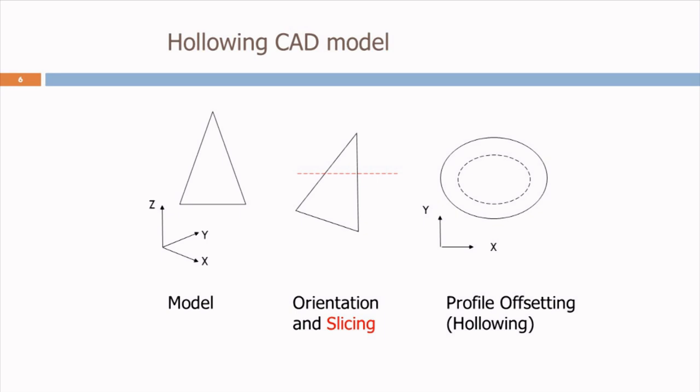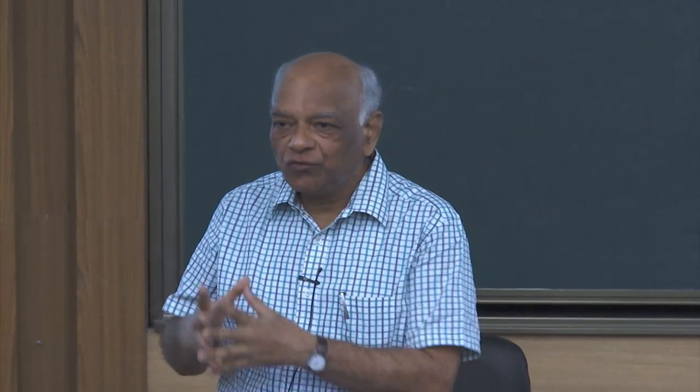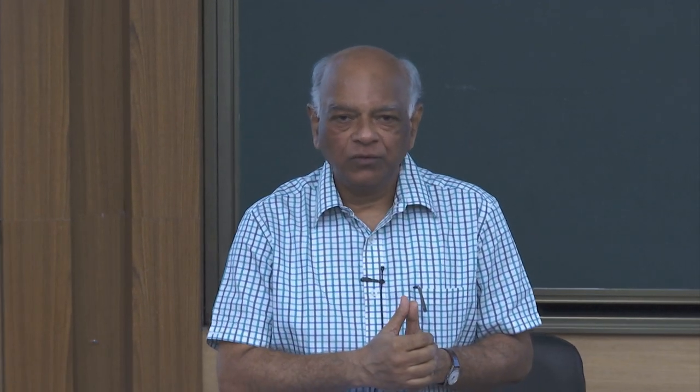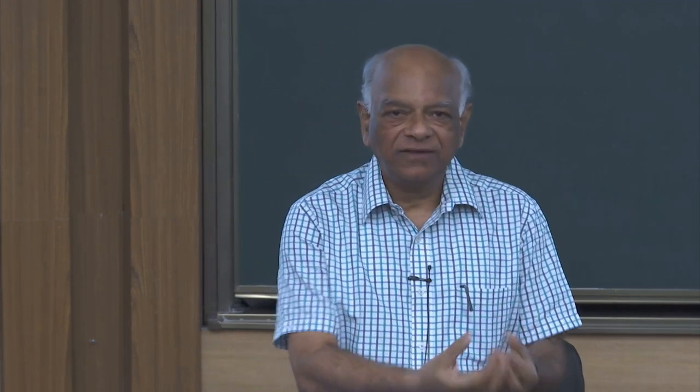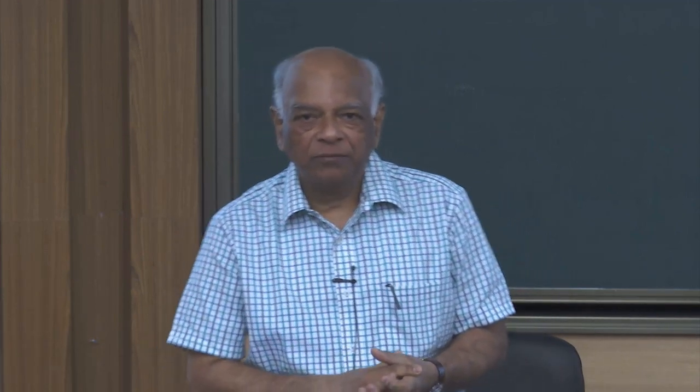When you are hollowing a part, the inside profile is not that important. It is just for saving the material. But the outside profile is still very important. If you are using it as a pattern, essentially for creating a sustainable or expendable pattern, you will see that the outside profile has to be very accurate, because that's where the part is needed. The inside profile is just an approximate profile that saves the material.